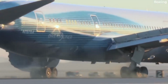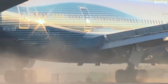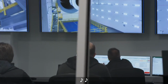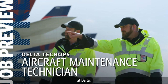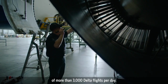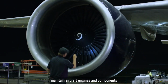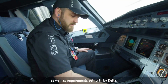14 CFR Part 121 Operating Requirements: Domestic, Flag, and Supplemental Operations. Title 14 CFR Part 121 establishes the operational rules for air carriers flying for compensation or hire. A domestic operation is any scheduled operation within the 48 contiguous states, the District of Columbia, or any territory or possession, conducted with either a turbojet aircraft, an airplane having 10 or more passenger seats, or a payload capacity greater than 7,500 pounds.